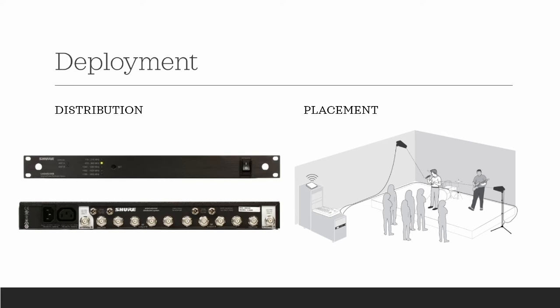What we don't want to do, and what I see very commonly when we set up wireless systems, is plug the antenna directly into the back of the unit. In some cases, we'll have the wherewithal to remote the antennas onto the front of the unit, but generally speaking, when I see non-audio professionals set up wireless systems, we have a lot of problems with our antenna placement. Basically what ends up happening is we end up in the back of a rack at waist height, without a direct line of sight to the transmitter.